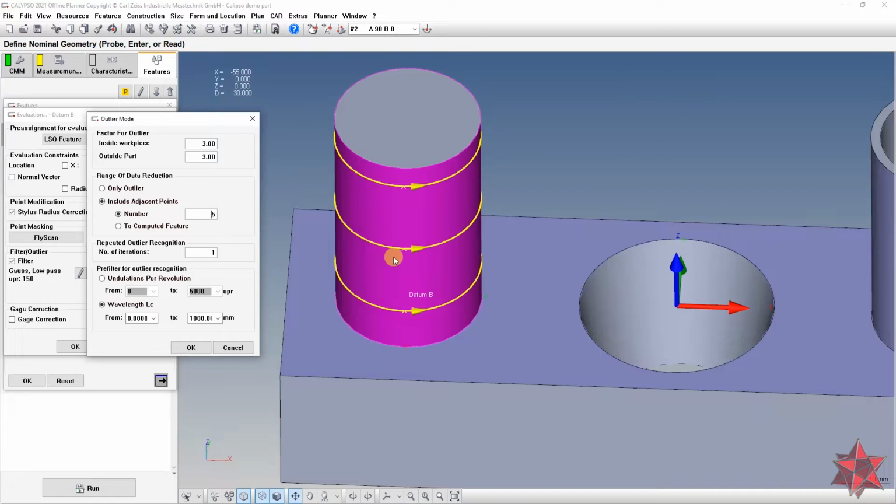Go and see with your own eyes what the machine does, what the CMM does. Go and see exactly how it touches the part, if the stylus is the right length, if the stylus doesn't touch with the extension. Go and see if there's any dust on the part, any grease or anything that can influence your machine. Check the temperature, check the humidity, check everything if you want to make sure that everything is fine, especially when you are measuring for a functional check.